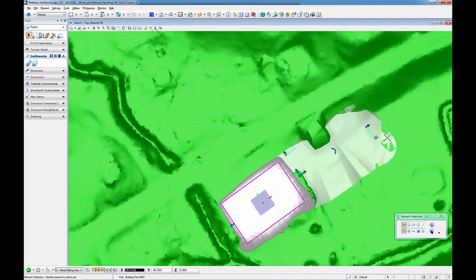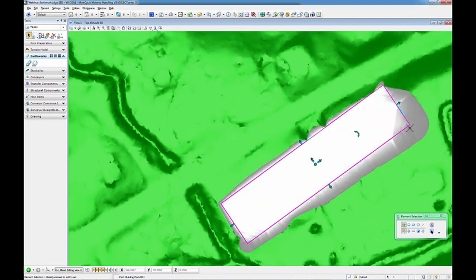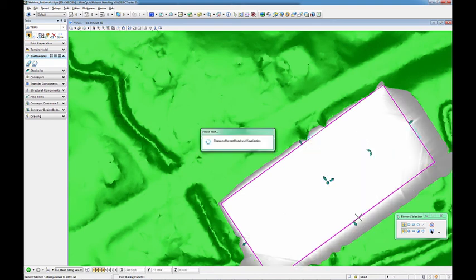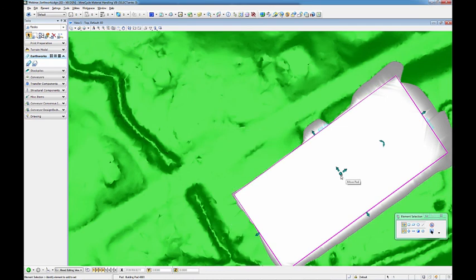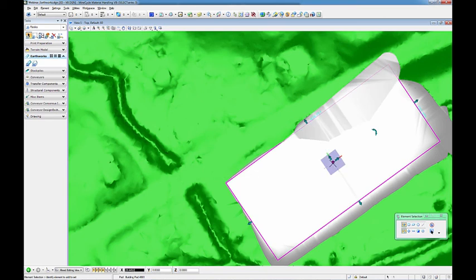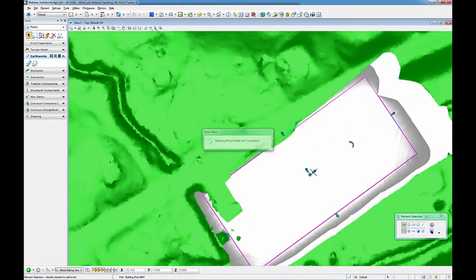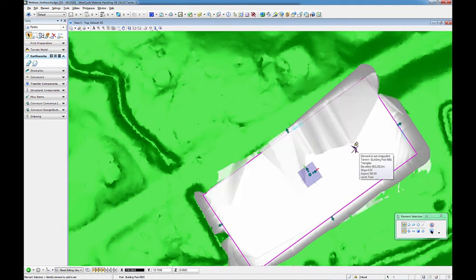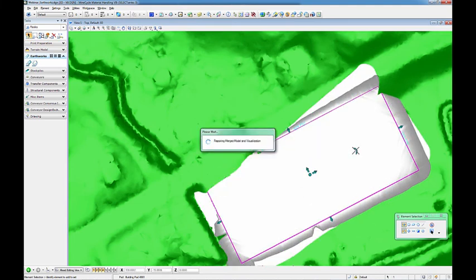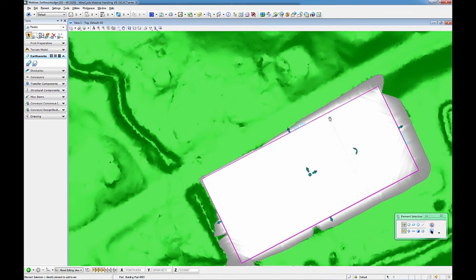Offset from the terrain is calculated from the intersection point, but a number of options are provided to more accurately define this. Site pads are parametric, so underlying geometry can be easily modified using graphical interactive manipulators. Manipulators are provided to alter the width and length of the site pad, to allow movement in the direction of the length or width, a free movement option, and the ability to modify the orientation. Dimensional parametric properties can also be modified to effortlessly update 3D model geometry.